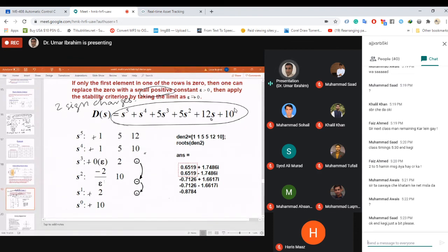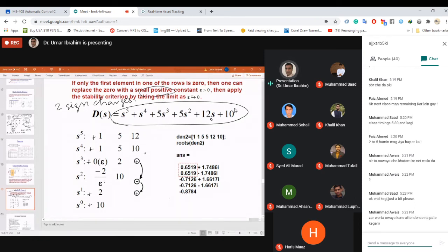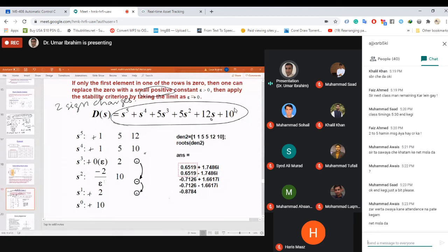And once we have the Routh stability table, part 3 of the analysis is to interpret the first column of values of the table to look for sign changes. Based on the sign changes, we can tell how many poles are in the right-hand plane, or unstable poles, or we can tell for what value of K or Kp, for what variable in the closed loop transfer function, the system will remain stable. Clear?